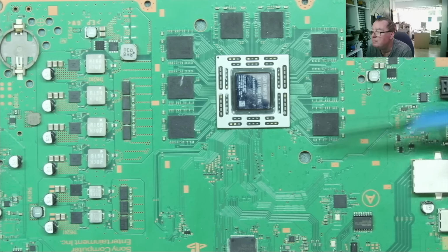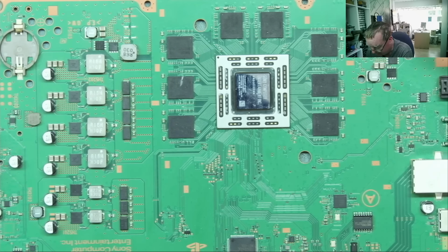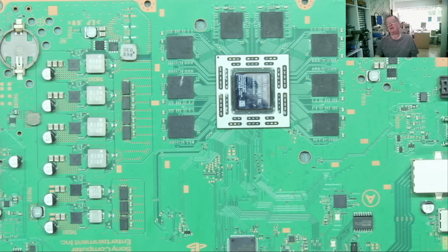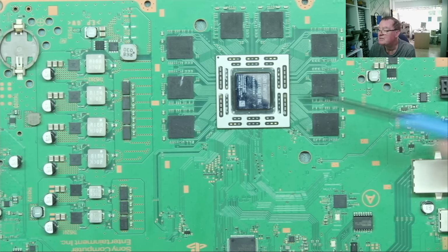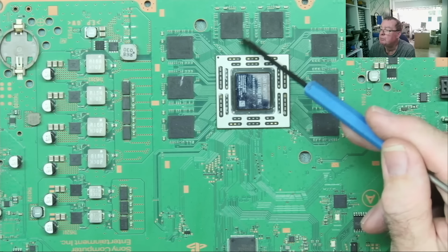Another common misconception with this type of fault and repairing this type of fault. There are some terms that we hear: reflow, reball and replacement. And then there is the "heat it up with a hot air gun and it'll work again." Often people call this reflowing. But what reflowing means is get this hot enough to melt the solder balls.